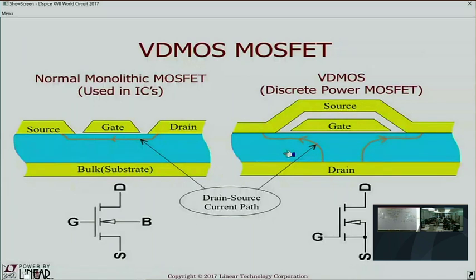The difference is, well, this has a body diode, this is a substrate diode. The difference is there's this body diode over here to the side. There's no substrate, but it has a body diode here. But that's not really the issue. I mean, you probably don't want to put current through your body diode. You can, but usually you don't. So that's not the big issue. The big difference is the Miller capacitance. There's a dramatic difference between these two structures.